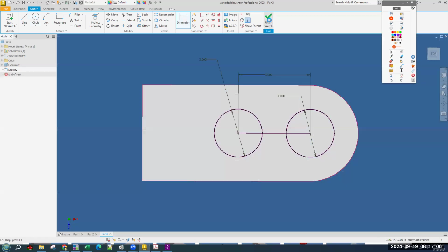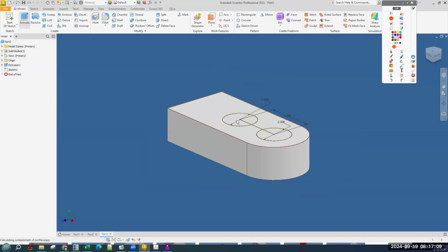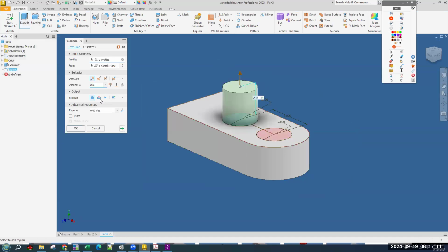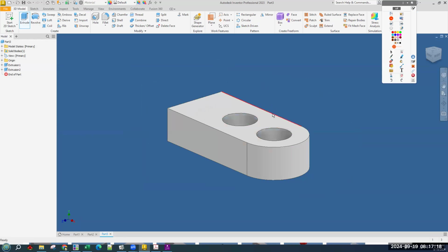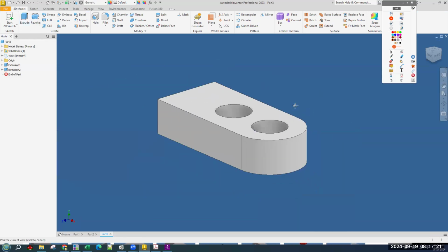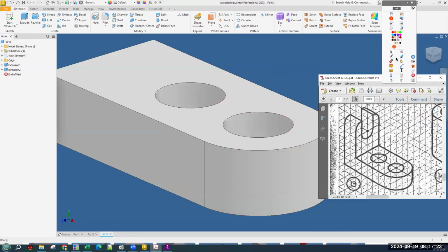And we can finish sketch, extrude, and choose the things that we just drew. Switch it to cut and through all. 3 inches apart. Right? And this other part, we'll just do it the same way. It's only 2 this way, the full distance front to back. And its total height, 1, 2, 3, it's 5 tall, I think.